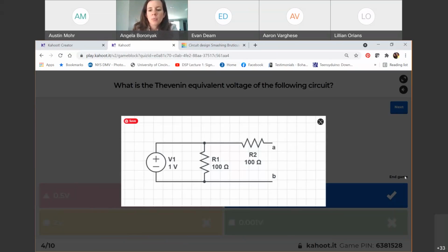Good. 0 volts, because it has no current that can go through it. It has no path. So it's like a wire, as in I didn't change voltage going from here to here. No change in voltage. Go all the way around, and I can see I'm 1 volt compared to B here. Or what's the voltage drop over R1? Also 1 volt if you chose to go this way, right?